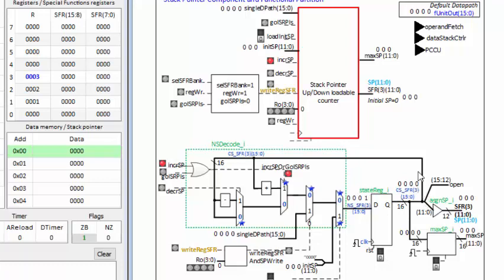The current value is 0, and if I follow the active labeled paths, the stars, you'll see that the stack pointer is incrementing through, and on the next active clock edge, the stack pointer will increment. And that happened before, but I just didn't see that. Why did that happen? It's because the signal increment stack pointer was asserted by the instruction decoder for this push instruction, and that controlled this multiplexer, which selected the current value through the incrementer and through, and then disregarded what's happening in the rest of the hardware.